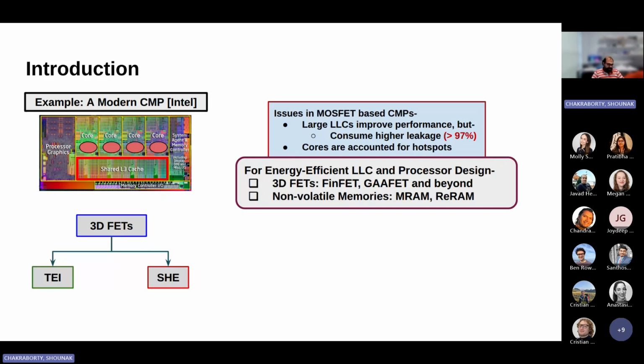But at the same time, high temperature is not good for the circuit health because of the presence of SHE. SHE stands for self-heating effect. These 3D FETs have some confined geometrical shape where the conductive filament or the channel is basically encapsulated by some thermal insulator that clogs the heat dissipation, which is really detrimental for the circuit health and can damage the circuitry permanently. So self-heating effect is bad.